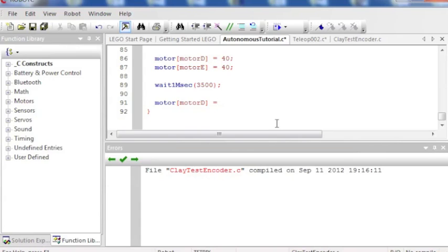It's going to execute all the movement, turning and changing of powers in less time than you intend, and you generally want to give the bot a bit of time to slow down from the speed you've got it at, which is why you set both motors to 0, so that it comes to a stop.